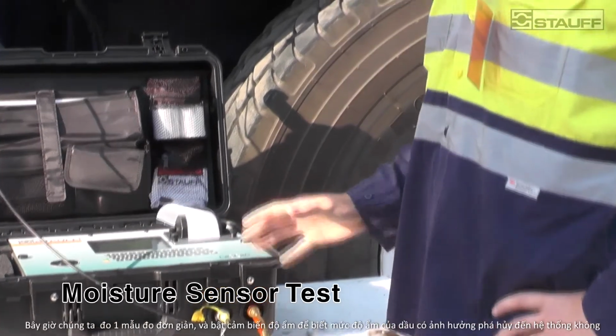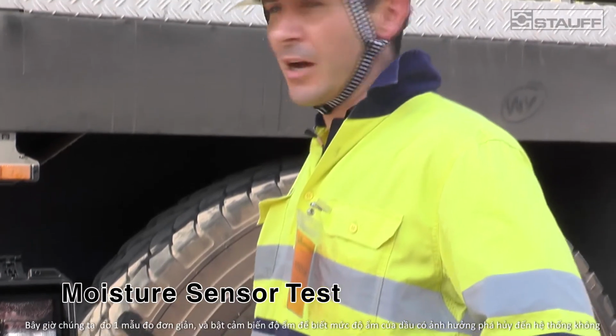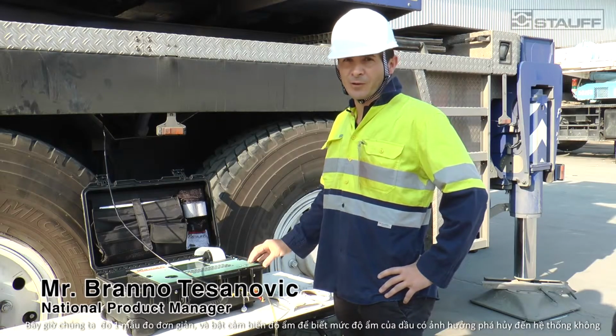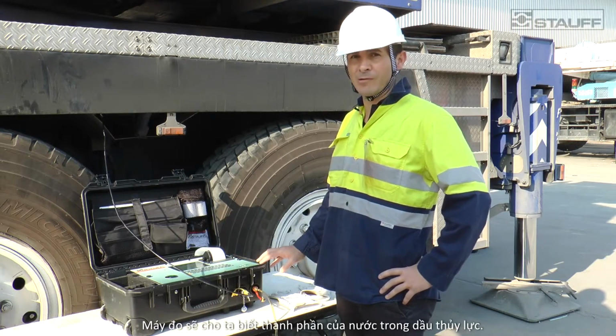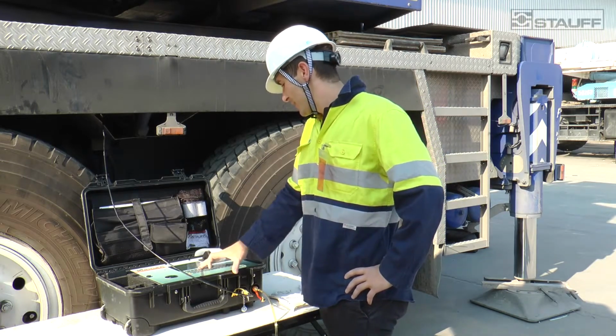So now we're going to do a similar test, but this time we are going to turn our moisture sensor on, as water is also very damaging to our hydraulic system. So we want to see the moisture content of the actual oil. So I just need to change settings slightly.